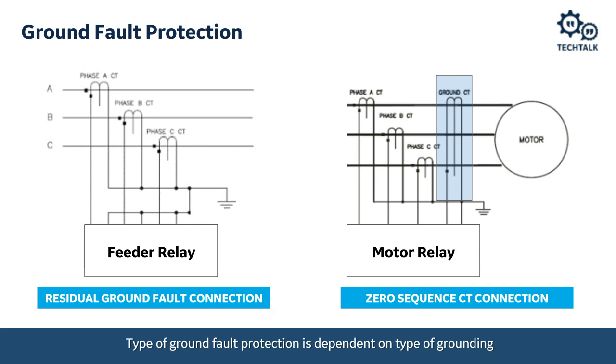Now, neutral overcurrent, for GE relays, are the calculated 3I0. So it's the calculated vector sum of the phase currents. That's for GE relays. And there are typically neutral overcurrent elements there inside of the relay.